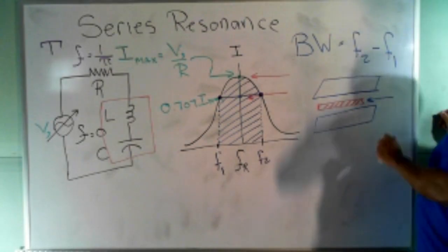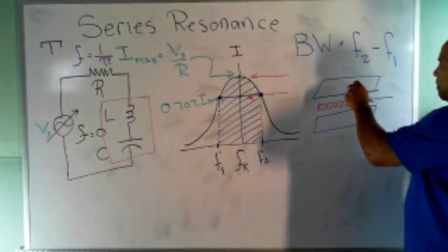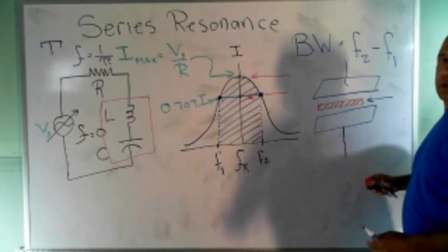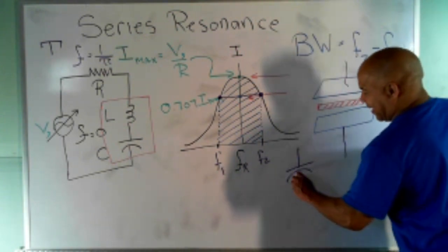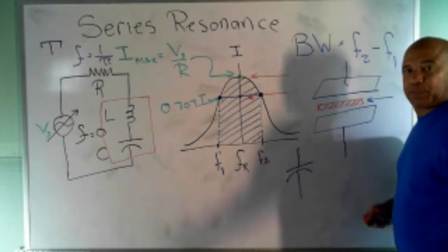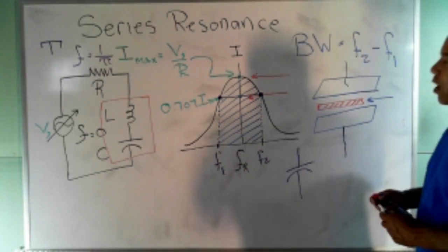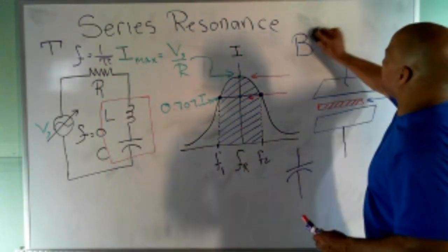So that's my insulator, and I make an insulator sandwich. I put a lead here, I put a lead here, and I can connect those two leads, and that's my capacitor. The symbol makes you think of that. Here's a lead, there's a plate, there's a plate. That one's bent because when it's polarized, that's the negative plate. So the formula for this, if you remember from DC,